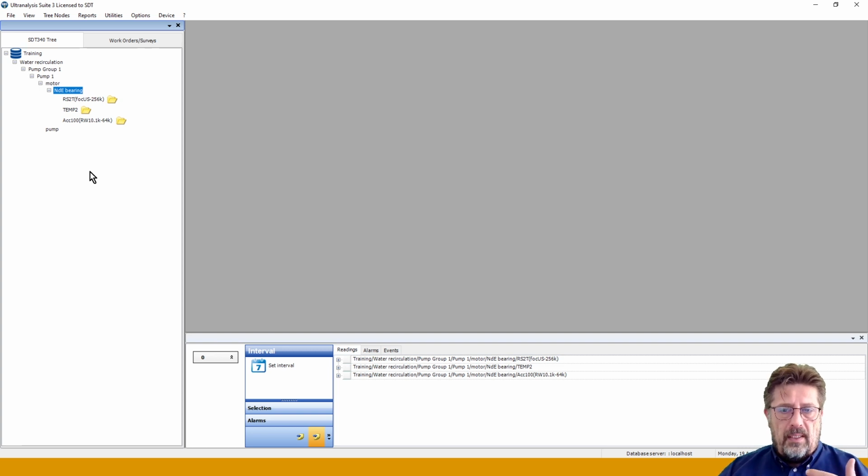And now I want to remind you what we said in the beginning. Don't make 1,000 measurement points and then go and work and realize you made a mistake in the beginning. So it's better that you make all your mistakes in the beginning, fix them, and then continue. After that, you'll be doing a lot of copy paste. It's going to be quite easy work if you do the job right the first time. So what we realize here is that we have a non-drive end bearing, but we need to consider vertical, horizontal, and axial as 3 different positions.